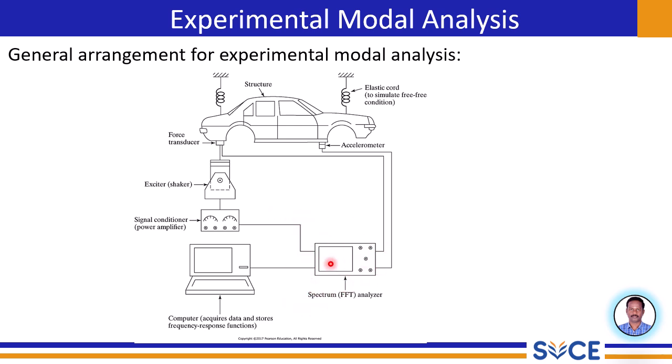The conditioned signals are then fed into the spectrum FFT analyzer from the signal conditioners. This is where the magic of signal processing happens. The analyzer takes the time domain signals from the force and response and transforms them into the frequency domain using the fast Fourier transform. This allows us to calculate the frequency response function, which describes the dynamic relationship between input force and output vibration at different frequencies.